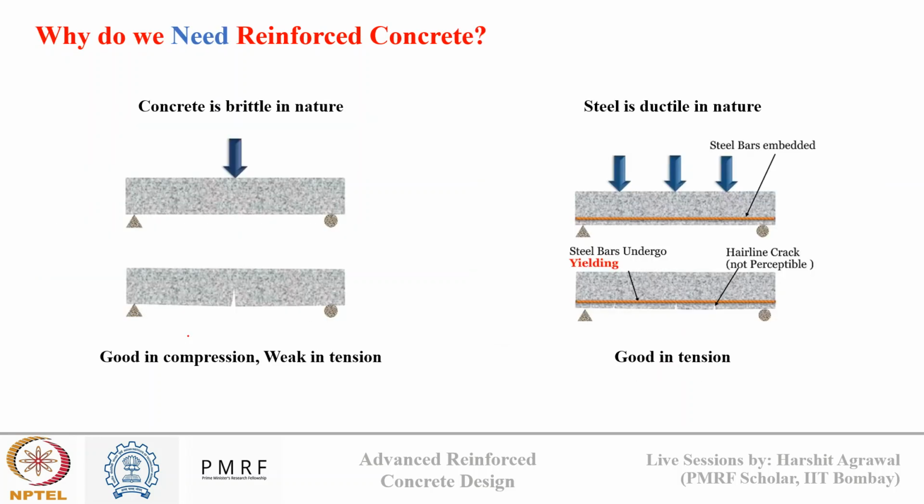design. Now, why do we require reinforcement, why are we emphasizing so much on reinforced concrete? If we see, concrete is a brittle material. It is good in compression but very weak in tension. So in actual application, there are both compressive load and bending or tensile load that act on a structure. If there is just concrete, it will crack easily in the tension zone.